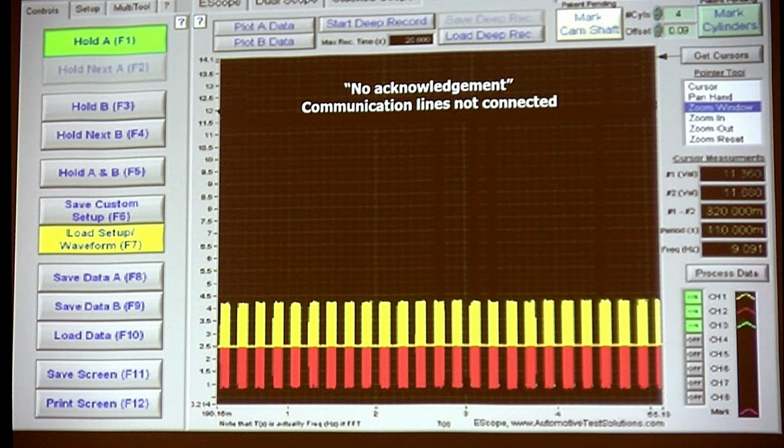No one can put that acknowledgement bit in for him. Nobody else is arbitrating, so he gets the bus every single time, and he puts the same message up. Can you hear me? Can you hear me? No one. This will go on indefinitely. So when you get onto a module and you see repetitious waveforms that look identical, what do you know? You know that no one can put a bit in, and if they don't put an acknowledgement bit in, he keeps asking for it. I've got a broken wire. That's what this is. And I do a lot of these, and this is the way you see them.